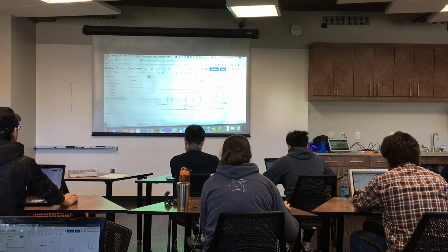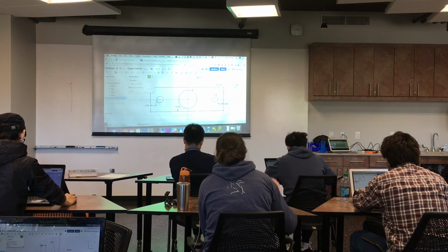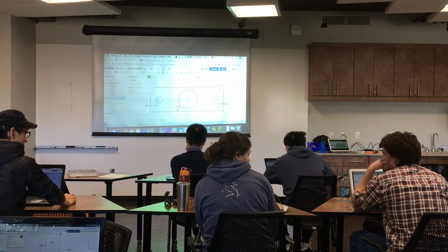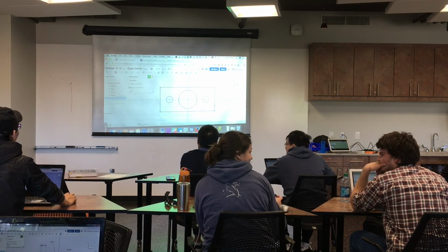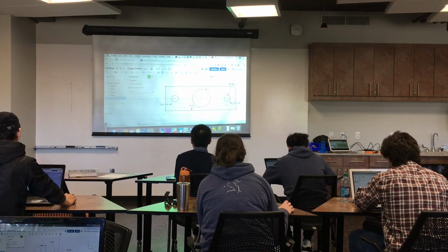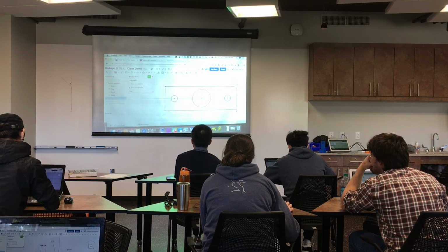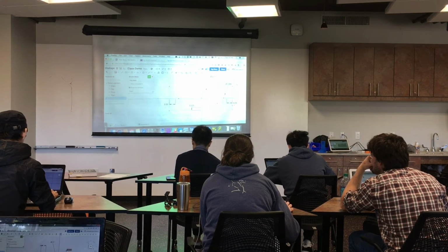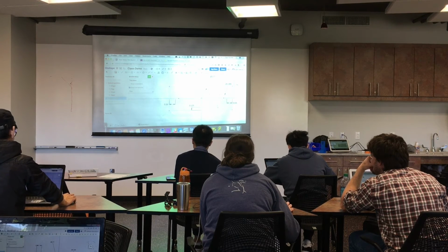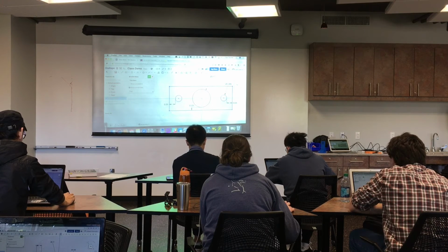And notice we still have some unconstrained parts. If you hit escape, we can click and drag, and you can see that I don't have the width of this constrained. So we could specify some distance from here to here, or we could specify the entire length of the thing. You could do it a bunch of different ways. For now, let's say that from the center of this circle to the center of the part is going to be 1 1/4 inches.